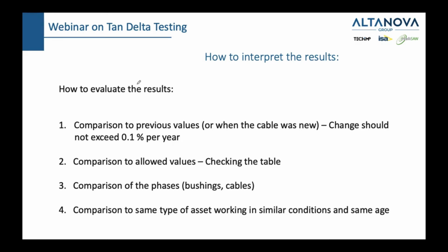This is very often the reason. It's a sign that you didn't connect something correctly. Another reason could also be that the grounding of your substation is not done properly, because then you are also not able to properly measure tan delta.